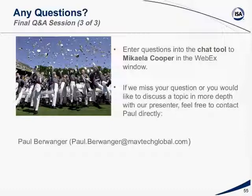All right, and the final question, what are your thoughts on alarm suppression and alarm shelving? Good or bad? I think there's a place for it, but it needs to be used judiciously. You don't want to shelve or suppress things that are really valid alarms. But if you keep getting these alarms, number one, either the set point's not set properly, so take a look at the set point. It needs to be set properly.